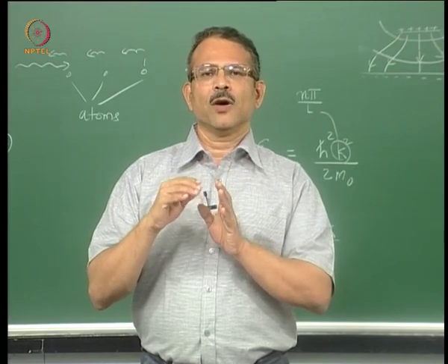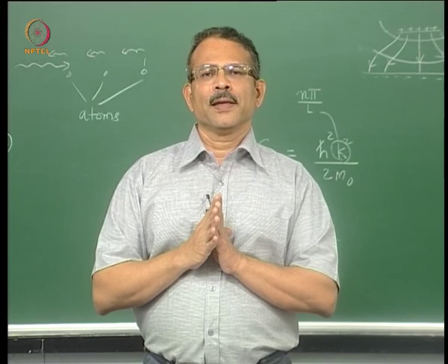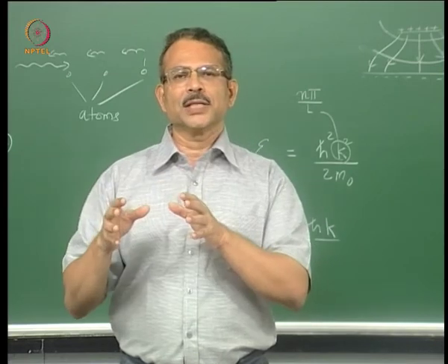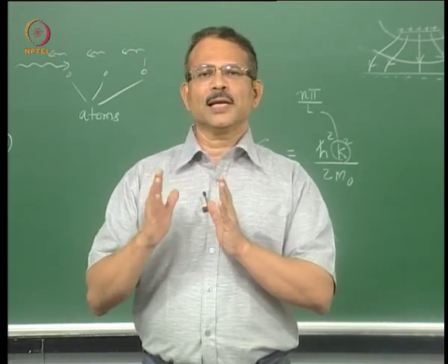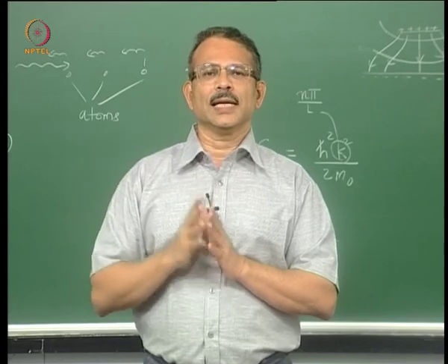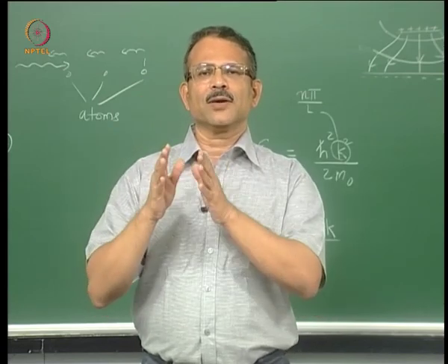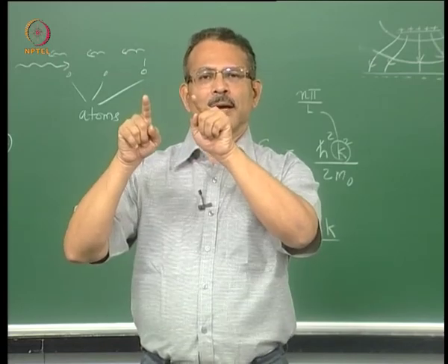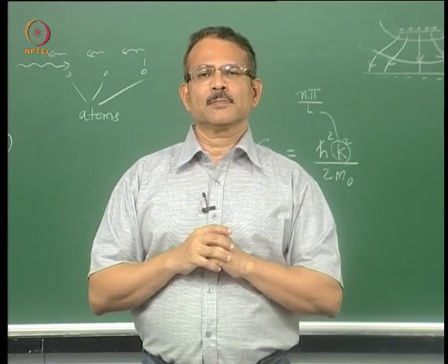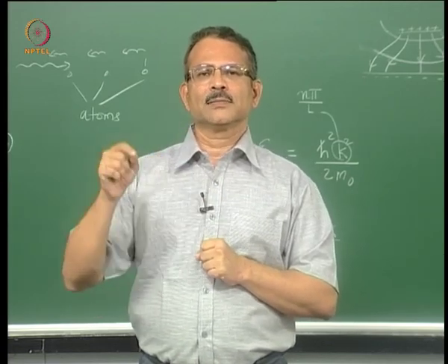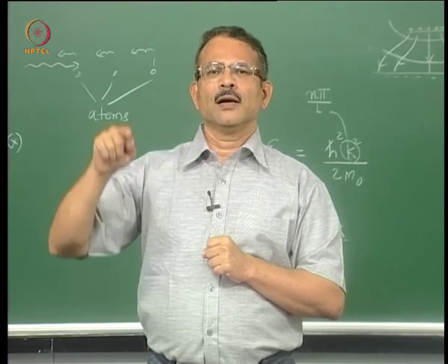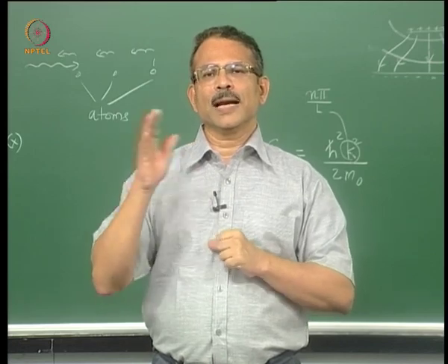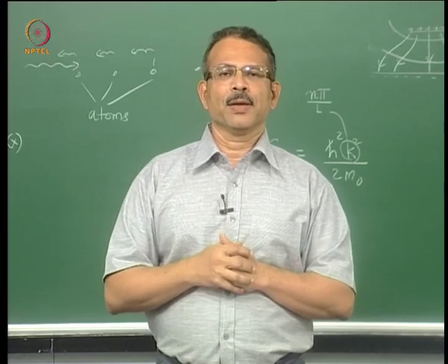results in the formation of discrete allowed k vectors for the electrons and therefore discrete allowed energies. The E-K relation is parabolic, but only certain k's are allowed and therefore only certain E's are allowed. So, the E-K diagram of an electron in an isolated atom, or an electron in a rectangular potential well, is a set of discrete points all falling on a parabola, which reflects the parabolic relationship between E and K.